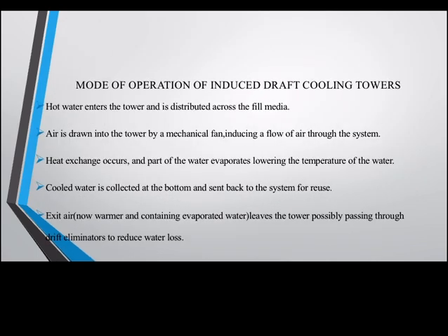So the mode of operation of induced draft cooling towers. Hot water enters the tower and is distributed across the fill media. Air is drawn into the tower by a mechanical fan, inducing a flow of air through the system. Heat exchange occurs and part of the water evaporates, lowering the temperature of the water. The cooled water is then collected at the bottom and sent back to the system for reuse.